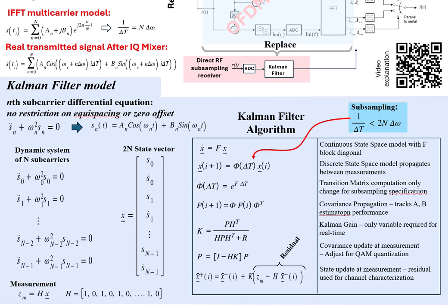Not shown on the poster, we can choose a single subcarrier frequency and normalize all frequencies to the single carrier frequency, so that all frequencies are very close to 1. With this normalization, the independent variable, that is time, for each subcarrier becomes carrier cycles. Thus, a single Kalman filter algorithm applies for all carrier frequencies.